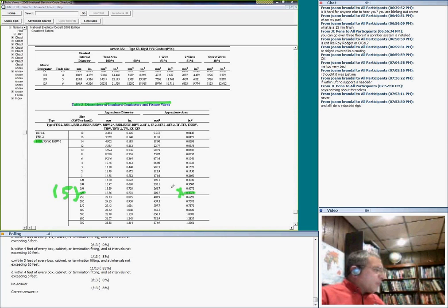You multiply this one by, let's make it even and say 10. I'm going to be using 10 conductors. I'm using conductors, guys, number 4. You multiply this by 10, and that will get you 4.754 inches. That's the minimum available space that you need to fit these 10 conductors, number 4.